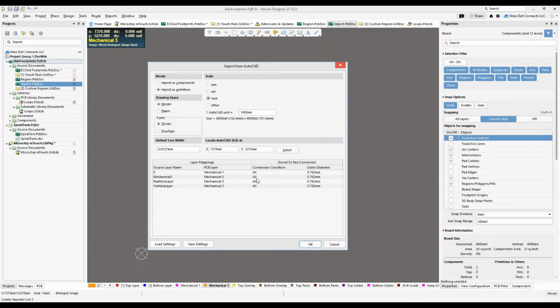Another area which kind of gets people a little bit tripped up is the layer mapping, because MCAD folks do use the layer maps, and so they put things on different layers. And it's always a potluck of what you're going to get. You don't know if they're going to give you the whole design or if they're going to give you just the socket that you're looking for. So the first time you run it through, you may just want to leave well enough alone. You press OK, and you realize, oh, there's all this stuff, and it's all in these different layers. Maybe I just want everything to be on a single layer. And that's what I did here: this one came in multiple layers, and I ultimately said, I want all mine just to come on Mechanical 3 because that's where I'm going to be working.